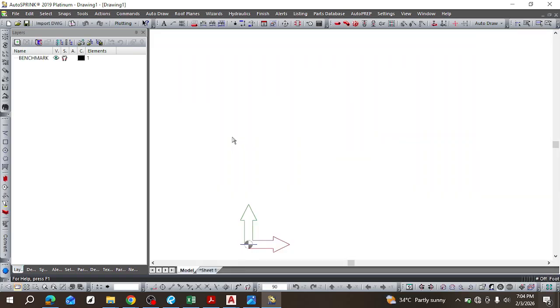Import it, turn off some layers, put on this view thing, and then lay out your pipes according to the pipe sizes, and so on and so forth. Lay out the pipes, then elevate, raise them to the correct elevation. Still taking some time. Okay, it's opened.